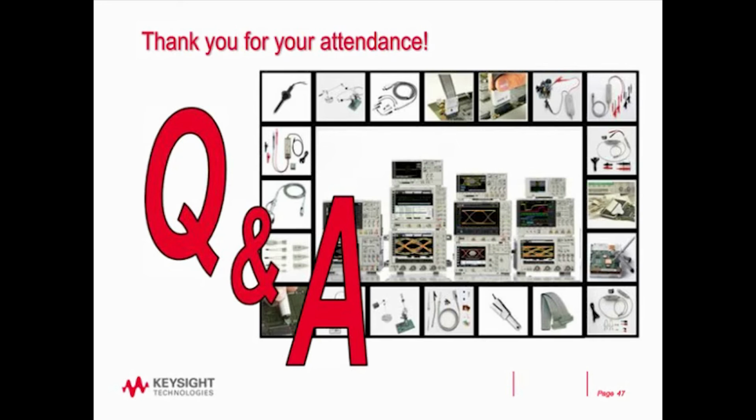First of all, you talk about calibrating the probe. This is something I didn't mention. One of my competitive colleagues really hit on this a few months ago. There's a degauss button. Probes will build up a magnetic element on them, and they will drift and build up a DC offset. And you have to continually degauss them and then recalibrate the DC offset.